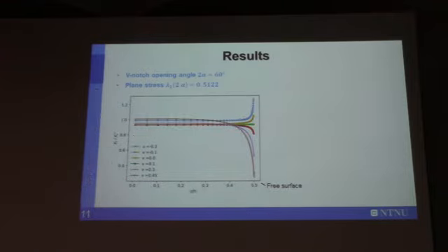And here you can see the stress intensity factor normalized by the applied stress intensity factor. Here we have something interesting: for a Poisson's ratio equal to 0, we have the same behavior as before, so no effect of the corner point singularity, while for positive values we have a decrease near the free surface. Then with the negative Poisson's ratio, we have an increase of the notch stress intensity factor.